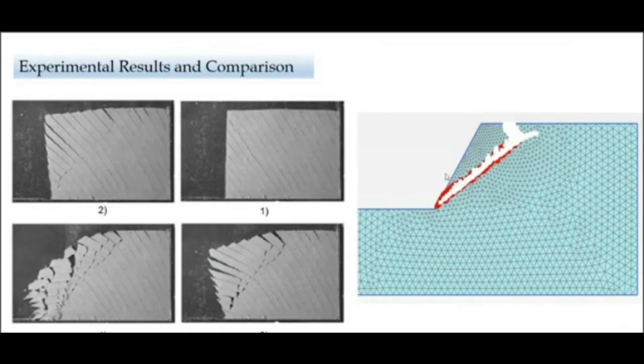So this is how you can use your jointed rock mass model to evaluate the mechanisms of failure in rock slopes. This can also be extended to your tunnels in rock mass. I have been using it and I found very good results compared with what has been reported in the literature and in research articles. For some consultancy purposes also, I have seen that Plaxis 2D gives very accurate results which correspond well with the instrumented field data.